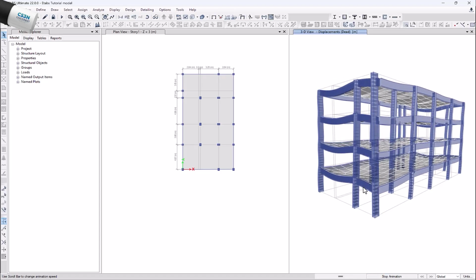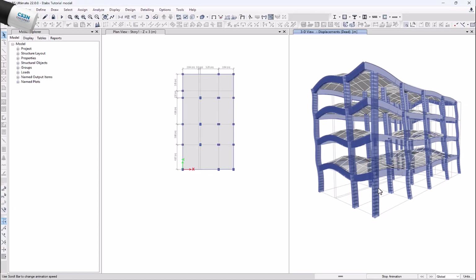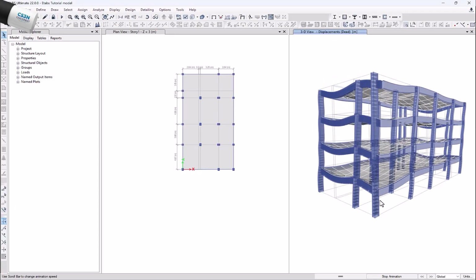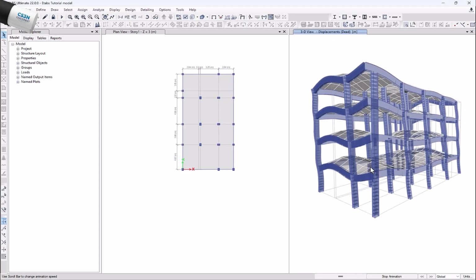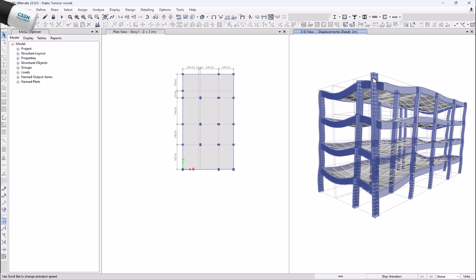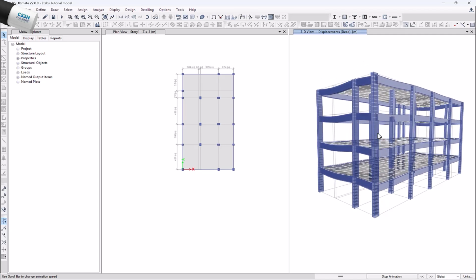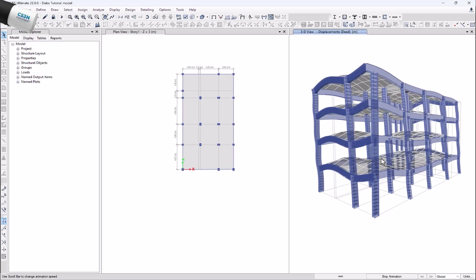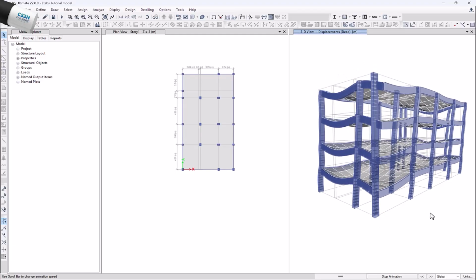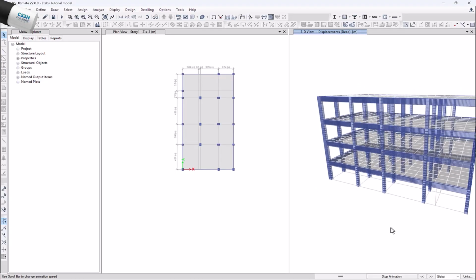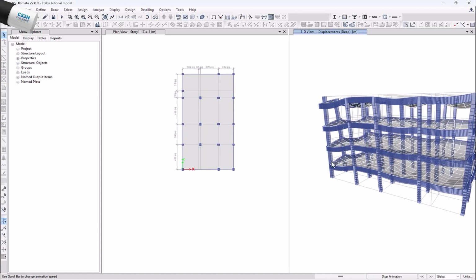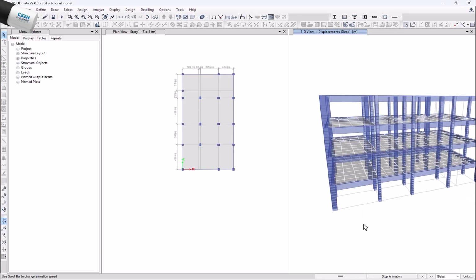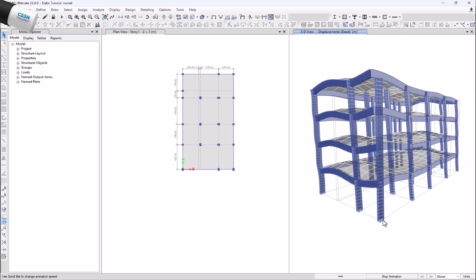What you need to see from this animation is that everything is linked together. Means you don't see this column flying away by its own, or this one, all moving together. But as you can see here for now, this column isn't moving, and that's why we got a warning message. See, the whole building is dancing up and down, and this column is just standing upright. And that's wrong. It's supposed to move up and down.